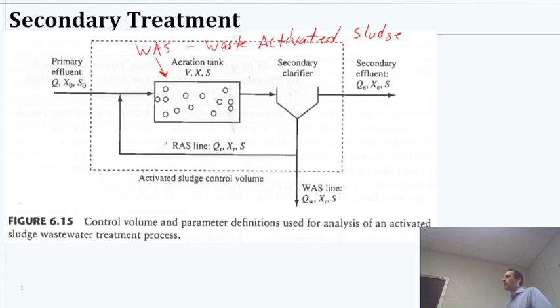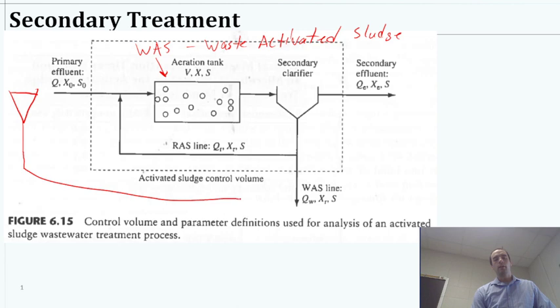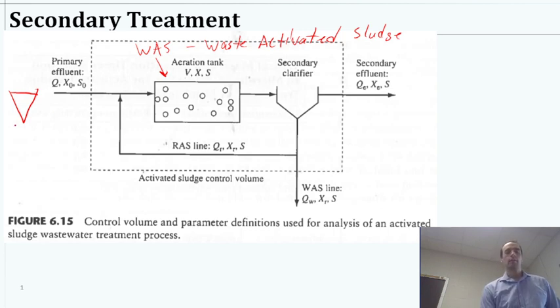So our aeration tank, that's doing the primary job. Then the clarifier, this will be the secondary clarifier, right? Because we have some sort of primary treatment on the left where we had some sort of a screen or bar rack, and then a clarifier here that would probably join up like that. I'm going to avoid confusion there and just leave that as a side note. So that would be our primary treatment, and then what we would call primary effluent would be the secondary influent. Okay, does that make sense? It's discharging from the primary step and into the secondary. So when we deal with word problems in wastewater, pay attention to effluent versus influent, right? That's going to tell you where we are in our system.